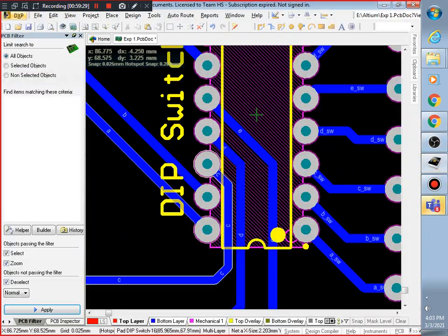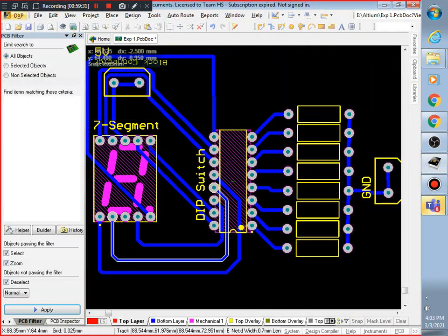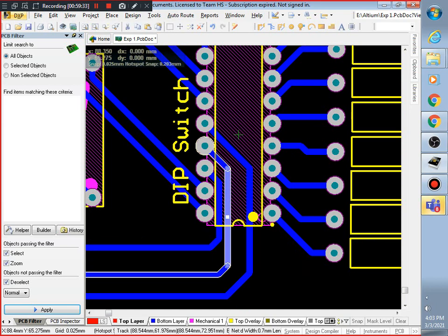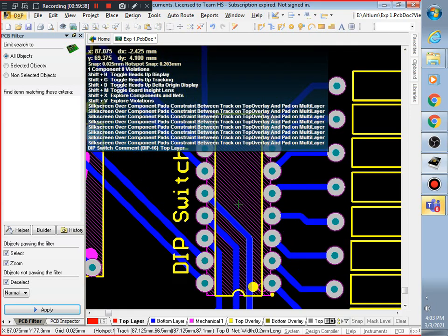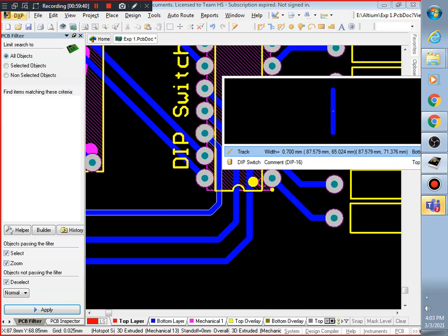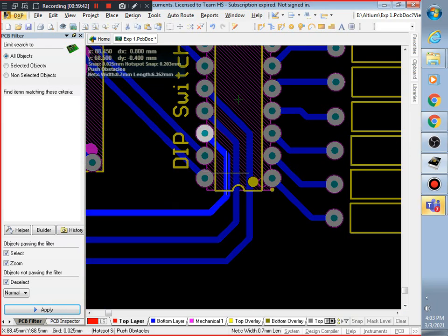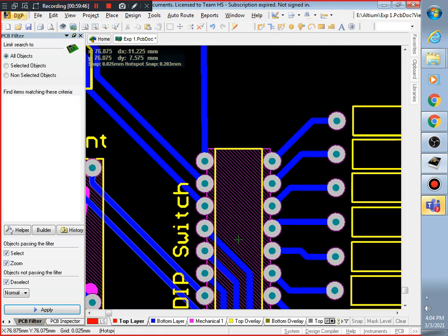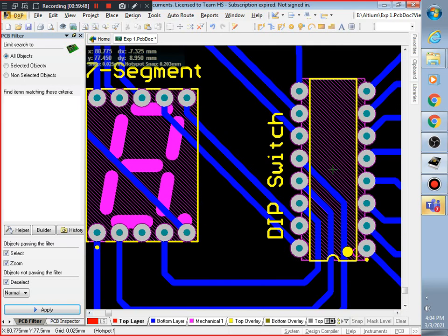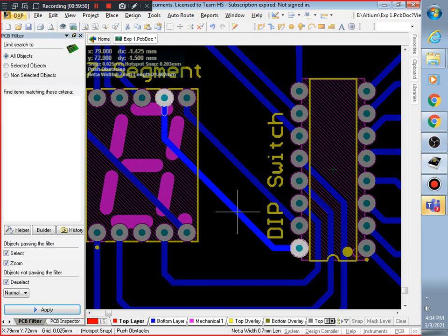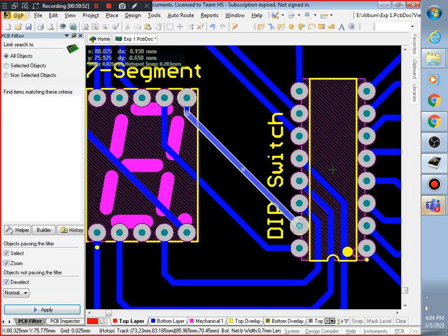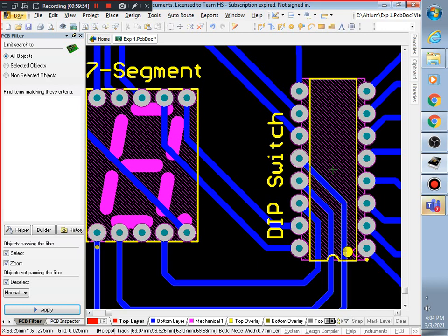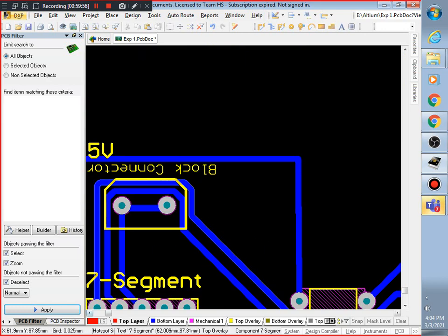Okay, anyway, so this PCB is rerouted over here. What I'm doing now, I'm just clicking on this one and dragging it, because these are very close. When this PCB is practically going to be made, this is going to be very difficult to actually make. So I just moved them into the ample space over there, and this one is also done like this. I can make this track a little like this, and on this side also I can make it like this.